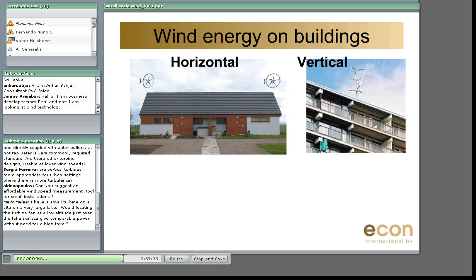Contrary to this, if you are on hilly or mountainous terrain, in a built environment with several buildings, or with heavy trees, you definitely have interest in gaining height, because in this case the wind shear exponent is 0.25, which means strong influence of height.